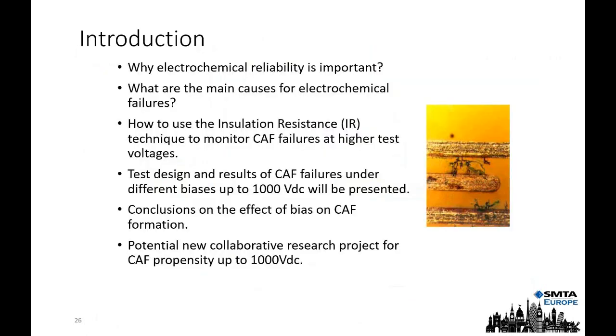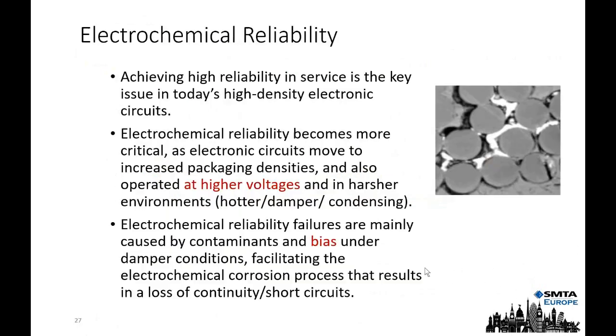In addition to that presentation, Martin will also be looking at obviously traditional failure modes due to condensation, contamination, and higher voltages when we look at the use of higher voltages in car systems for the future, and particularly testing for CAF at 1,000 volts. So that's an interesting issue to be considered.